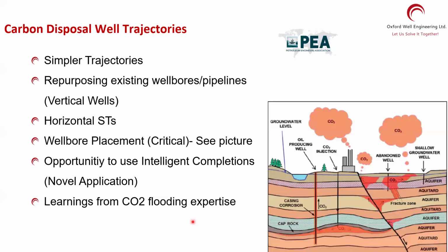People can also use fancier technologies like intelligent completion. They can put the intelligent completion in the vertical part, connect all the layers into one, open and close as you like, and pump into whichever you want to pump. So those things could be used.